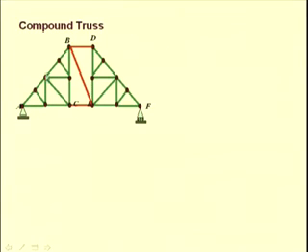So, this green truss that you see is a simple truss. In the same way, we see another truss D, E and F, which is again a simple truss. Now, these two simple trusses have been connected by the links BD, BE and CE to form a rigid truss, and this complete truss formed by connecting the two simple trusses is known as the compound truss, and it has been supported by a pin at A and a roller at F.